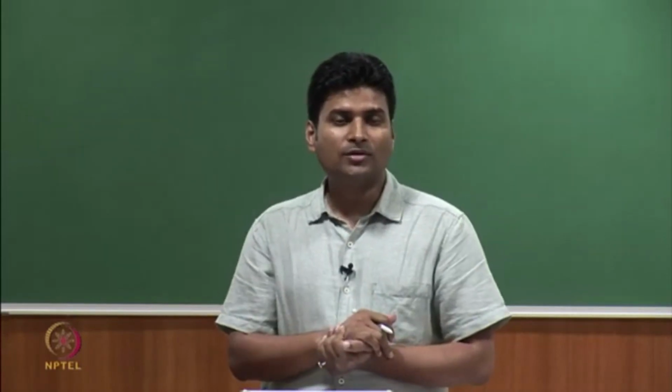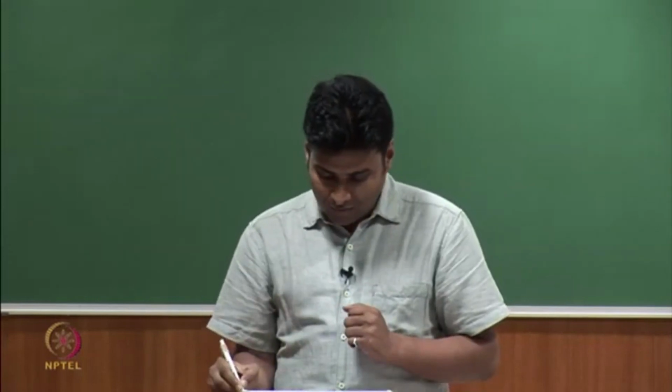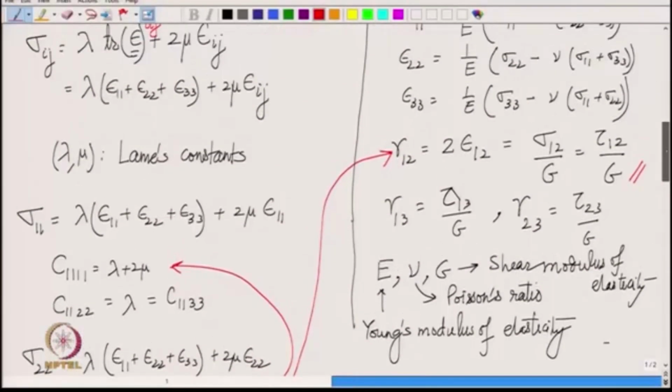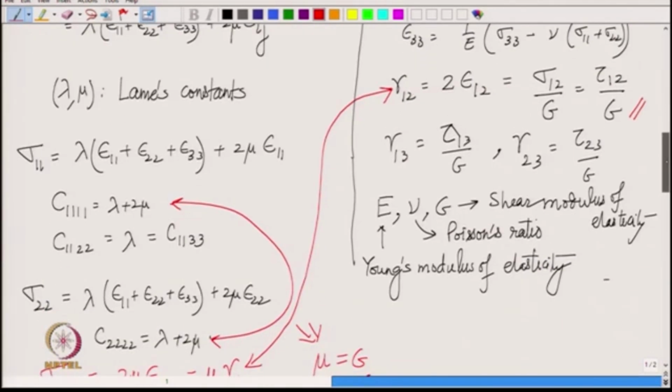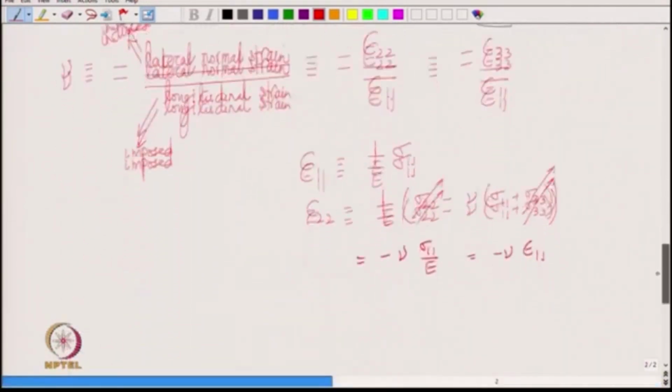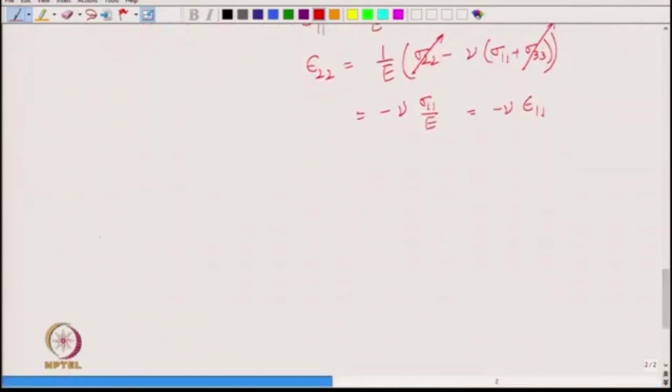How to get shear modulus? So, you see as from the formula, the shear modulus it simply says tau 12 is equal to G times gamma 12. So, if you can induce shear in the body and measure the stress, then the ratio of those two will give me shear modulus, is not it. So, to measure shear modulus G, what you can do is you again take your rectangular bar. Suppose I take a rectangular bar